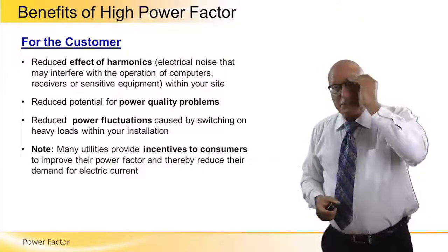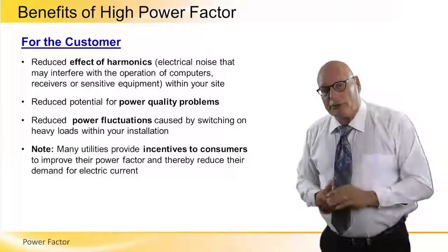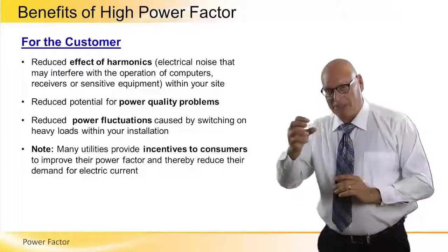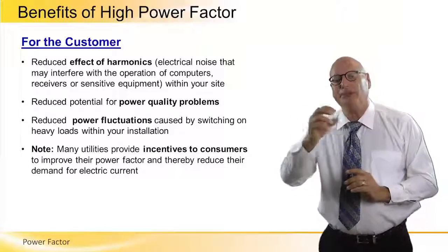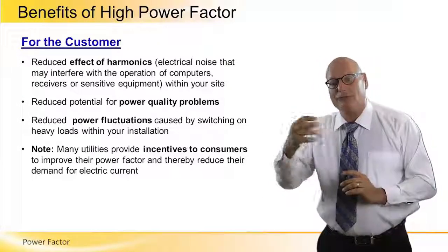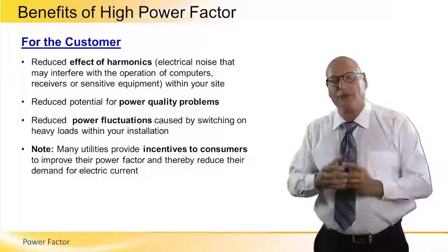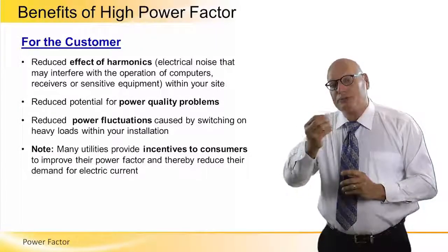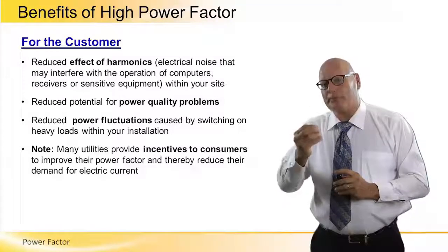The benefit is, if we have a better power factor, it will reduce the effect of harmonics, which is basically electrical noise that may interfere with operations of computers, receivers, or sensitive equipment within your site. It will reduce potential for power quality problems.